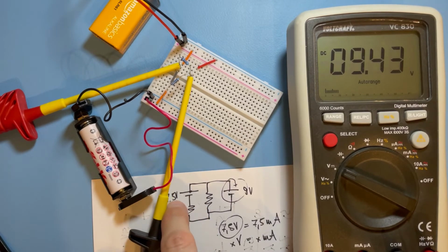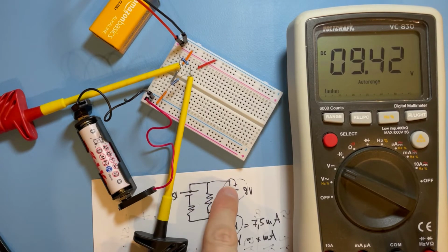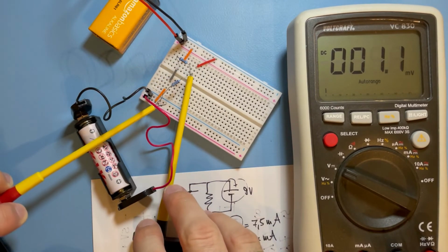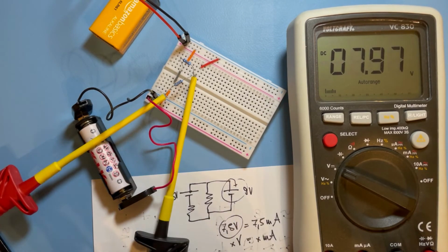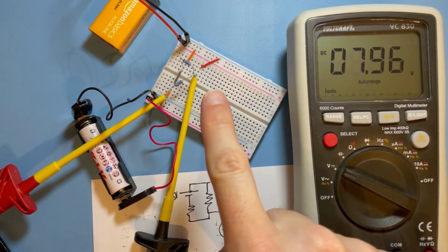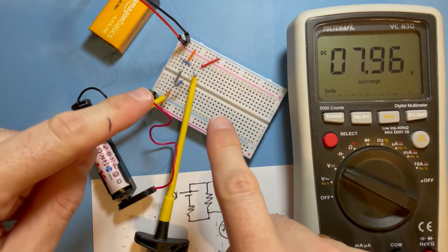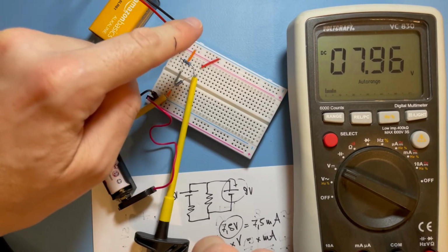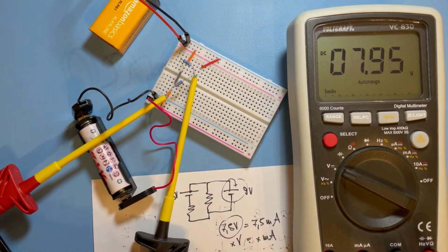So this battery only is doing something against the voltage of the battery in its own branch to the left, and not in the whole parallel circuit. Okay, and so in this branch where the battery takes effect, we have roughly 8 volts or 7.96 volts. And it's the same direction of current as you see here, the ground and the positive probe. And we drop voltage towards that point where these two join to the ground.